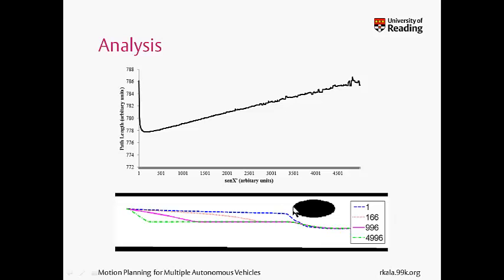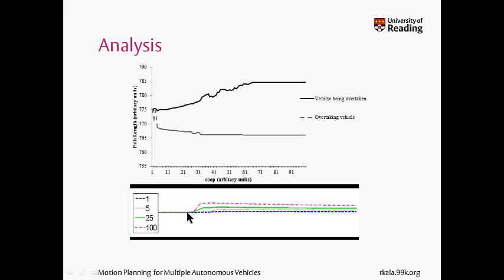And as I said, if you're too scared of the obstacle, you will travel like this. If you're not at all scared, you will travel like this, and this is how the path length gets affected. Again, if you're too cooperative, you will dip too much, and if you're too less cooperative, you'll basically travel straight. You'll give no sense to the other vehicle, which will now have to overtake using a very steep trajectory. So more cooperation means the path of this vehicle gets bad and the path of the vehicle actually overtaking gets good. A very high cooperation means there's a large difference in their paths. This vehicle is cooperating too much and therefore it has a very bad path length, and obviously this one has a very good path length. It does not have to do anything, it just needs to drive straight.